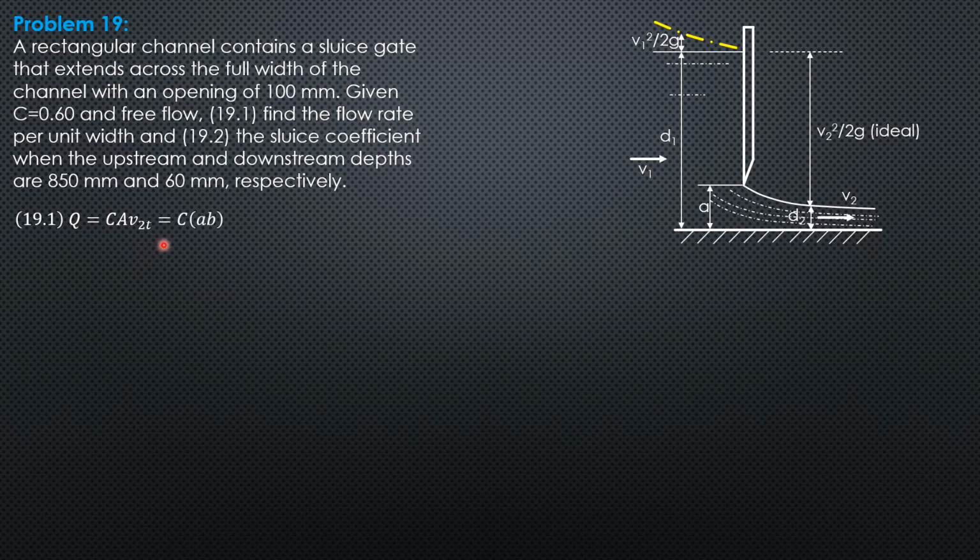The theoretical velocity at section 2 is equal to 1 over square root of quantity 1 minus quantity area 2 over area 1 quantity square, times, in the numerator, square root of 2g times quantity d sub 1 minus d sub 2. So you have to watch my lecture video first on tubes and sluice gates because this was explained there, or it was derived there.